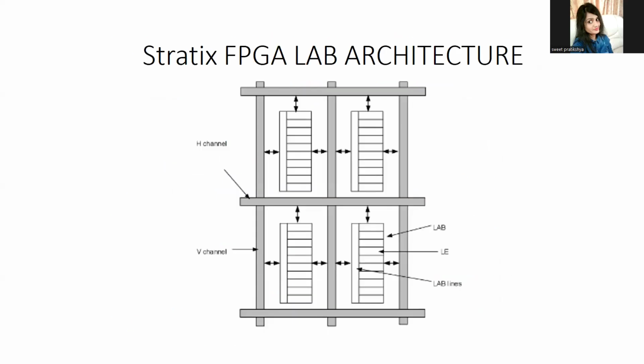Similarly, this is the Stratix LAB architecture. These LABs are similar in principle but more optimized for high-speed operation. Each LAB, in the sense of logic array block, includes 10 logic elements, which are used for advanced routing and pipelining and allow faster data flow. It also has design tools that take advantage of static layout to place timing-critical logic optimally.